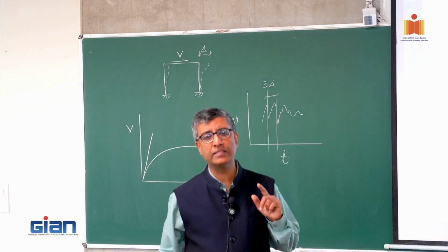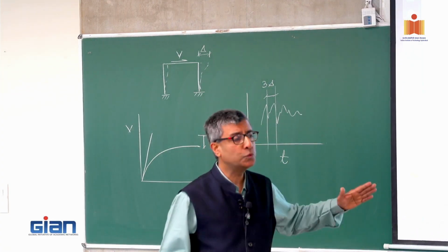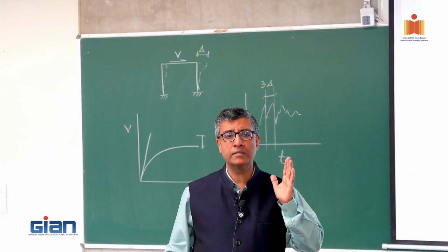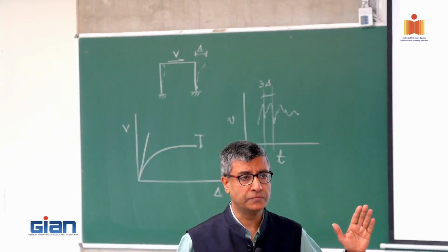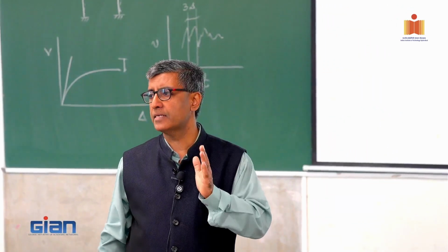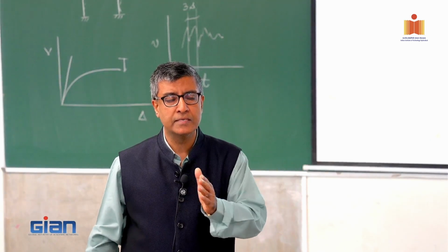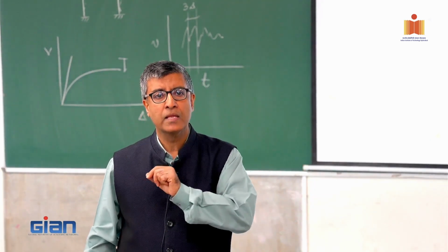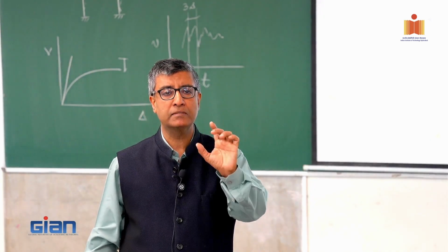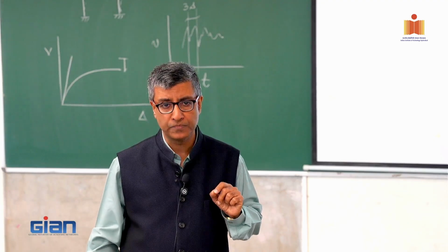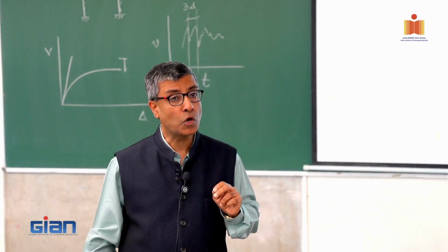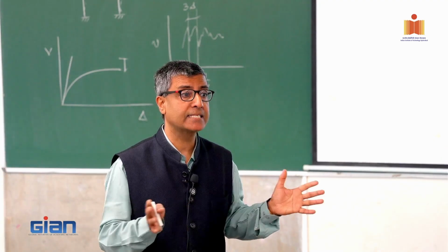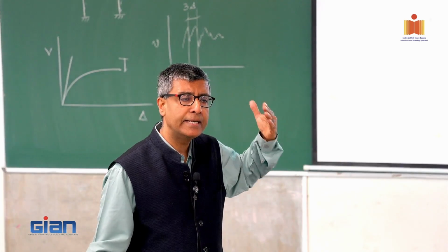There I take the maximum. And that too you study over the record of all the months in a year, over several years, see the distribution, and then you come up with this recommended value in the code. So do we get that from the windrose diagram? No, windrose diagram is about directionality. This is just a reading in a certain direction.